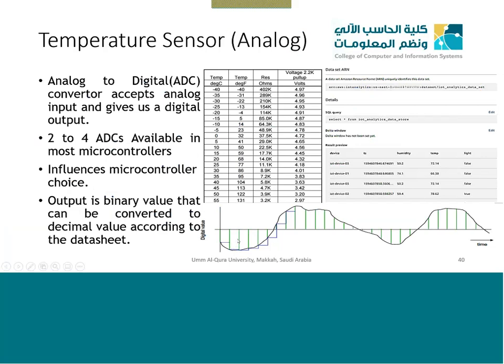We have these green places. We convert this data from analog, which you can see as the black analog curve, into digital values, fixed point. Of course, there will be some loss of accuracy, but now we will have some 8-bit or 12-bit digital data. Every temperature sensor company will give you a formula that once you have the 8-bit data from this sensor, multiply by this, divide by this, and you will get a temperature in centigrade or humidity in relative humidity units.